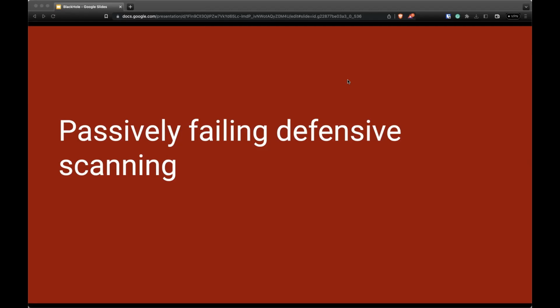So how do we find all of our OT devices? Well, some organizations have tried in the past to scan OT environments with active scanners like Nmap or Nessus or Qualys, and these usually result in mass outages and financial loss, which is often not reported. For this reason, security teams usually use a passive network monitor to listen for traffic on switches via taps or a SPAN port. And as long as you're able to access the appropriate choke points, you'll be fine.